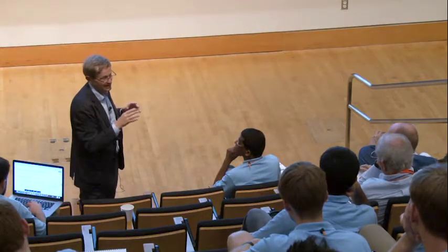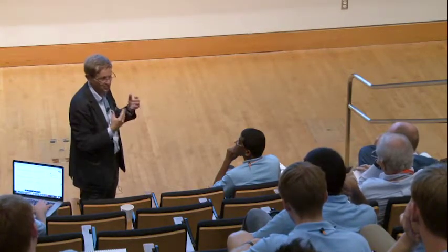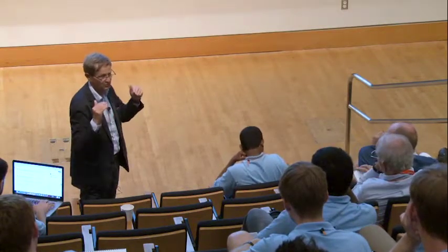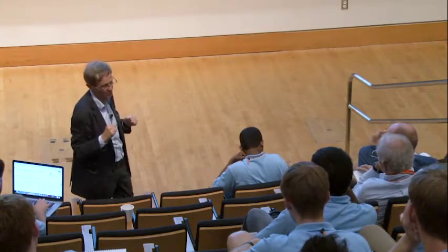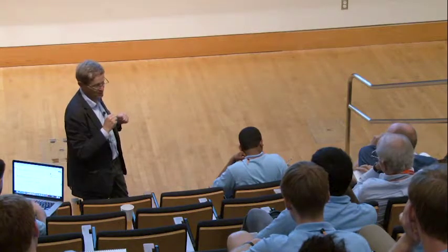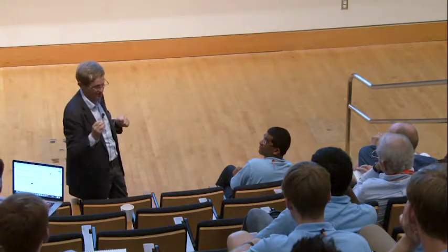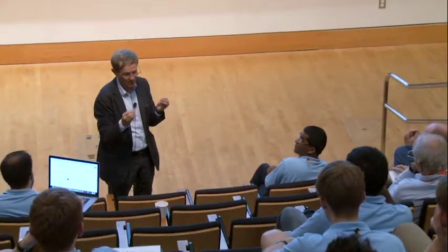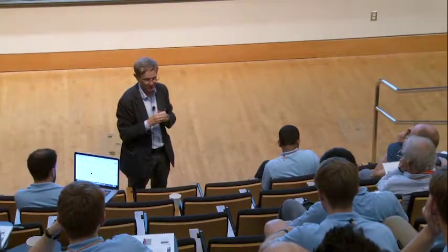It's the scalar product of the gradients of velocity. Essentially, the gradients of velocity produce the noise. If you want to reduce the noise from jets, you have to reduce the velocity. The very high-speed jets will produce a lot of noise. It grows like the Mach number to the power 8. So this is a result of Lighthill. Lighthill, I think, was the first to get the fact that the pressure is proportional to Mach number to the power 8. So as you increase the Mach number, it makes a lot of noise.